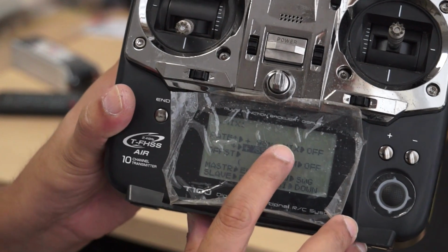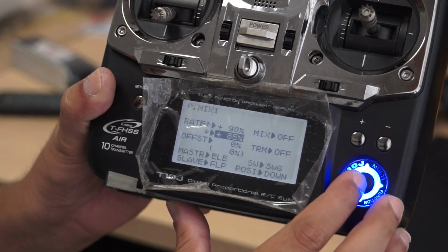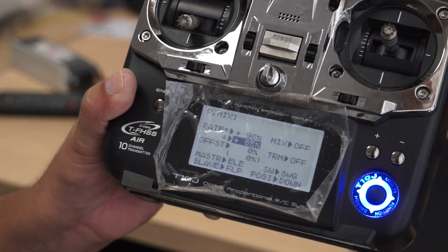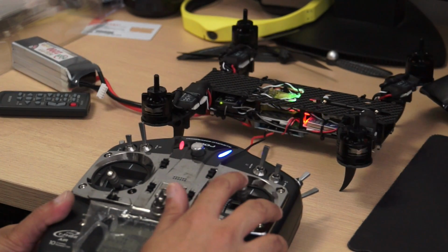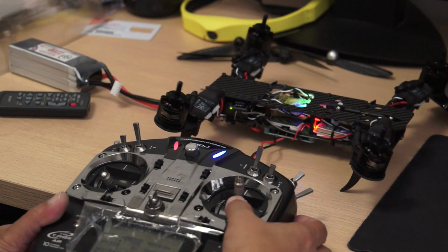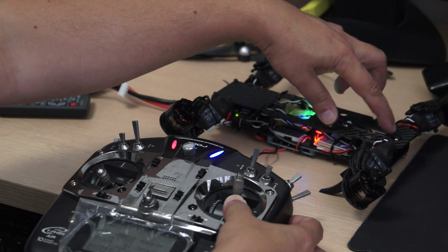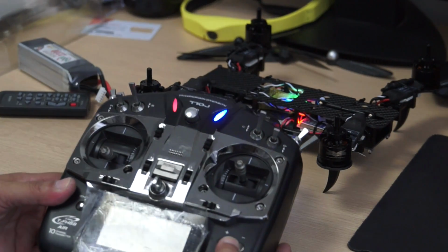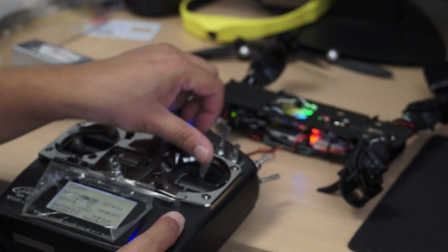Now for the values, you can see my values are 98% and 85%. These are my values, but your values could be different. Why these values? It's because when I turn on the tilting, dynamic tilting, I will go all the way forward and I will see if the connecting rod is hitting somewhere and the servo is buzzing. In that case, I will simply reduce this value. If I reduce this value, you can see the effect.